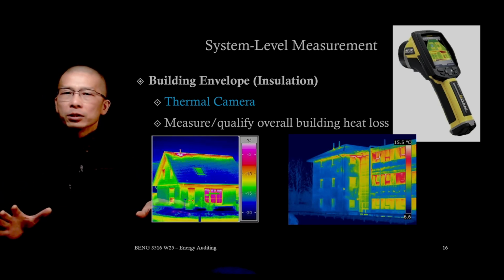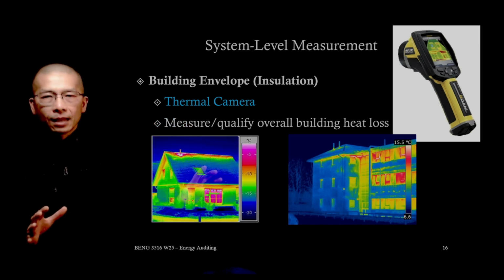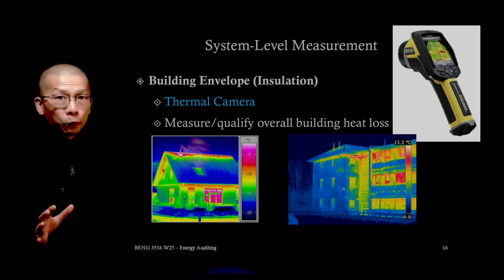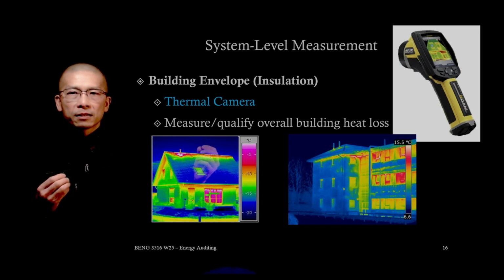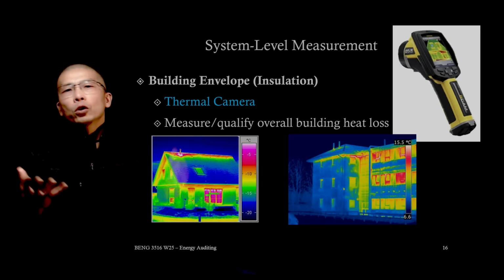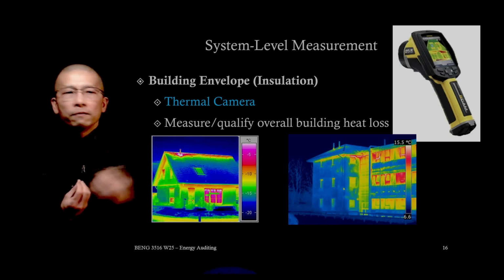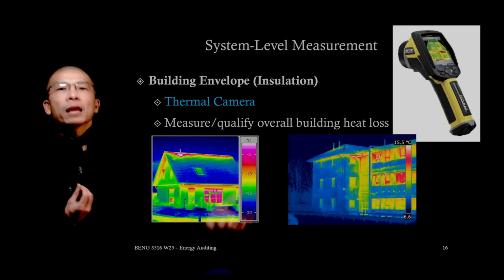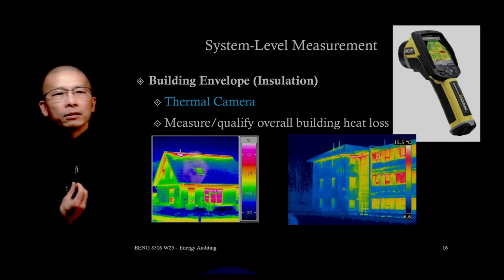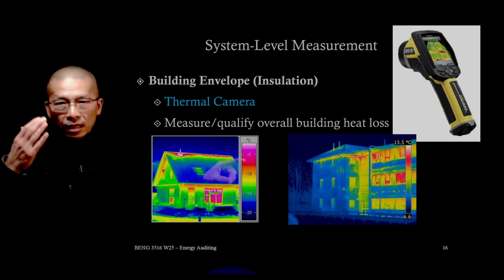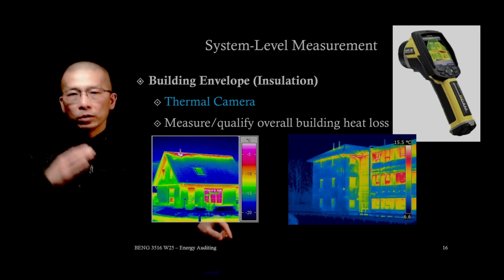An infrared thermal imaging system produces a video signal that can be displayed or recorded as a thermogram. It's a photograph of an infrared picture view that shows variations in temperature. The lighter, brighter colors are higher temperatures. The darker ones, right, are the lower temperature ones.